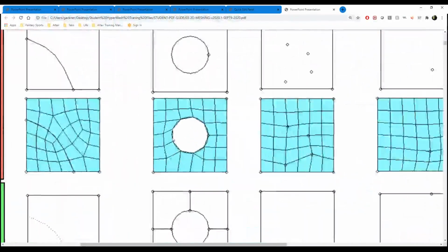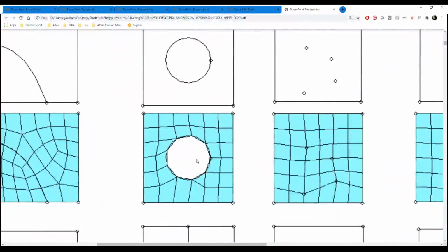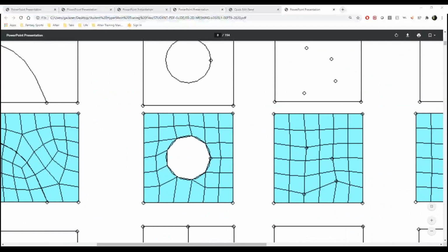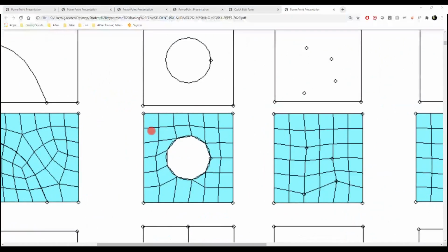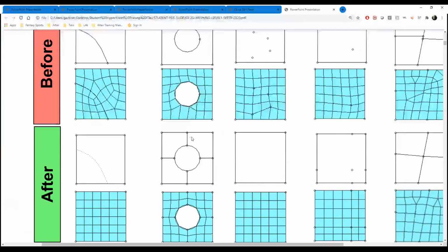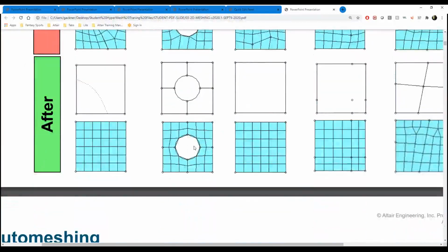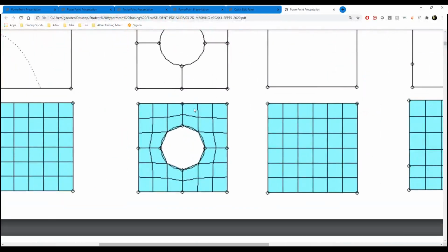So what I like about this next example, we got the plate with the hole in it. The first mesh that came out of there isn't perfect. It's not that bad. But one thing I don't like about this mesh here, if I bring my spotlight tool over, is I have a clear 2 rows of elements above the hole, but below it, it goes from 2 elements to 1 big element back to 2. It's not really consistent how it's handling the regions outside of that hole. What this user had done was, we're going to see how we can do this together in a moment, they actually split this region up into quadrants, and by meshing those 4 surfaces individually, well, they got a much cleaner and certainly more uniform mesh on the bottom mesh there.